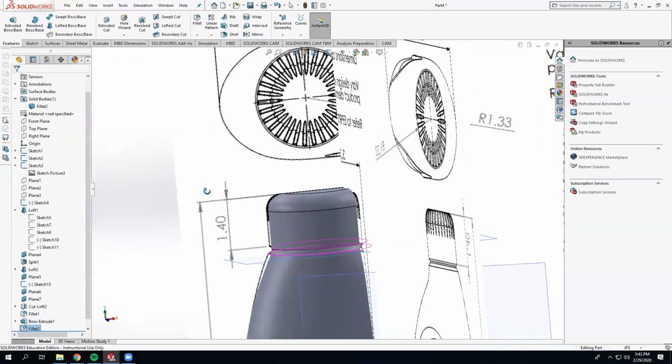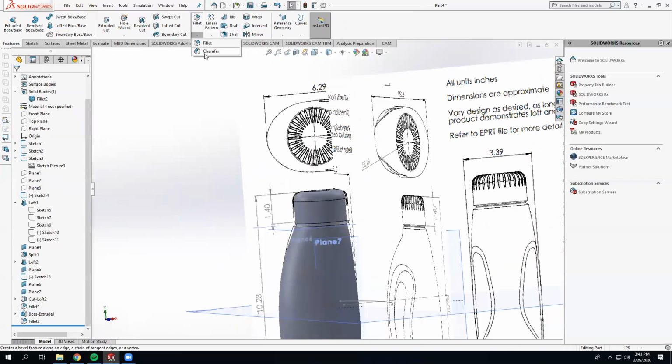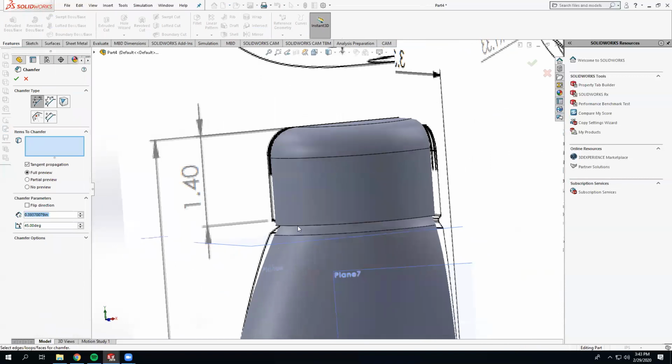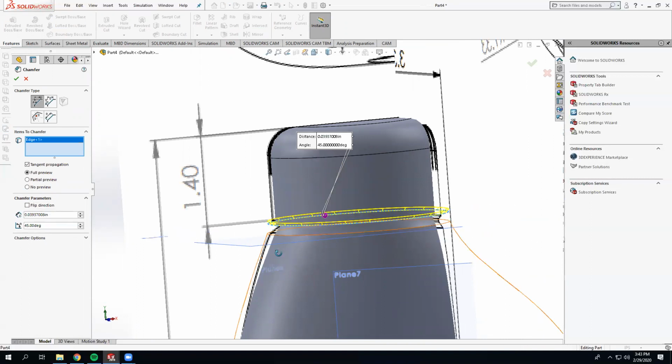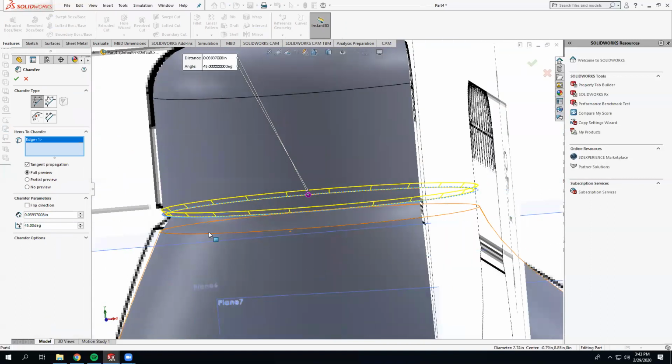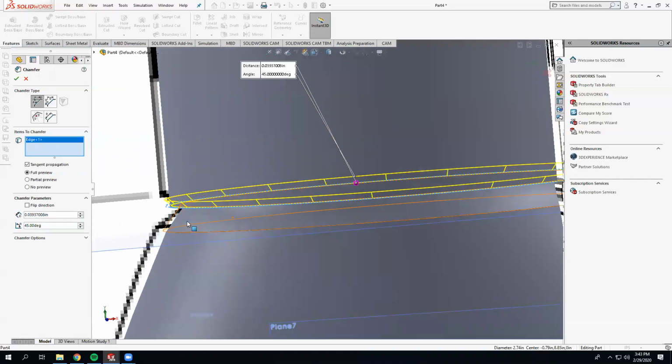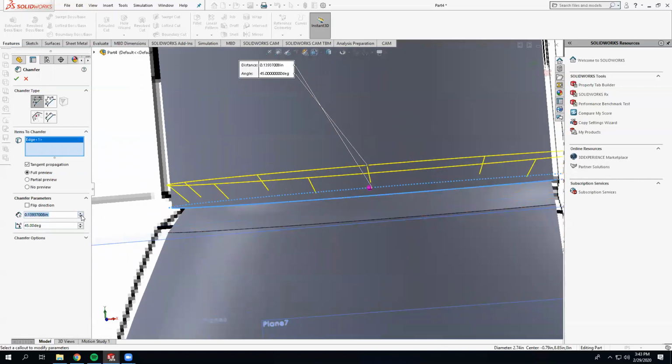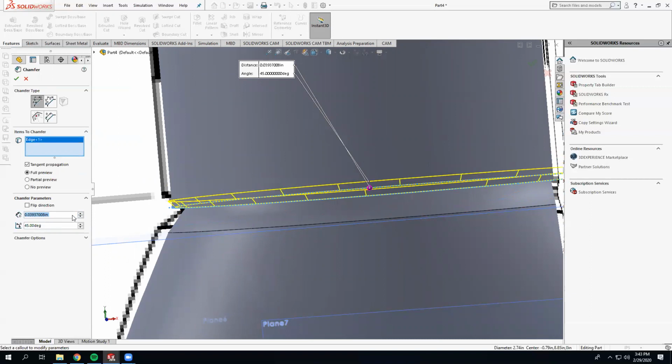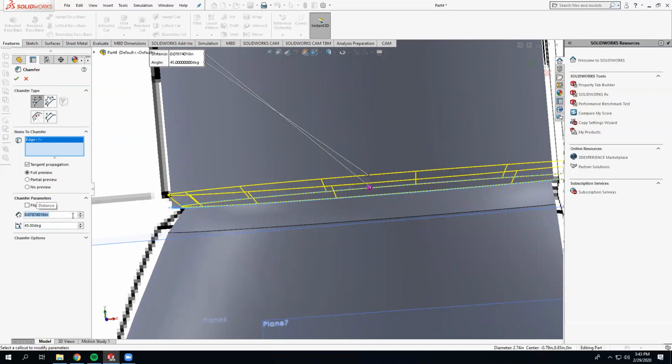Oh, that's okay, kind of match. Then that has a chamfer at the bottom. And if you don't get the preview of the chamfer, just put 1 millimeter, or just input a very small value, and then we can adjust this. So it might be 2 millimeters. And play with the angles. Click OK.